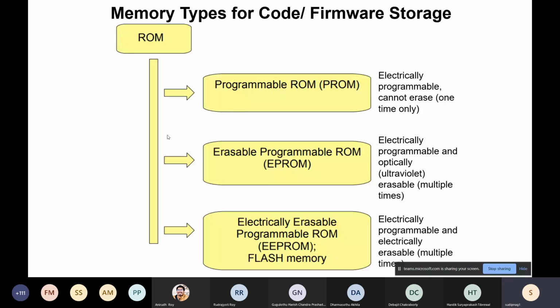And one reason being, there is a large amount of memory typically available, not in all microcontrollers, but many. So in those microcontrollers, even if you reserve one page of flash, let's say 512 bytes or 1024 bytes, you just keep that space or page, or even segment as some people call it, depending on how it is organized internally.